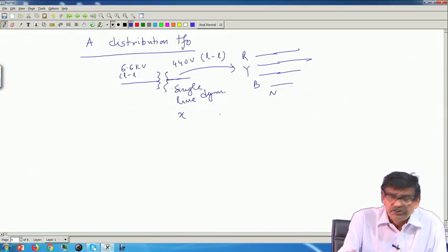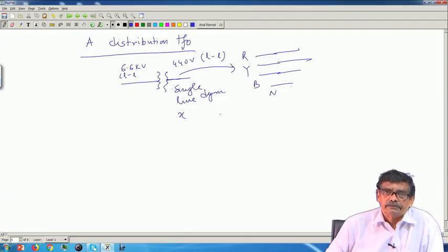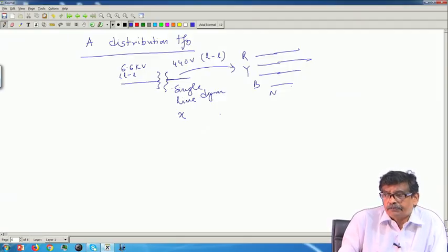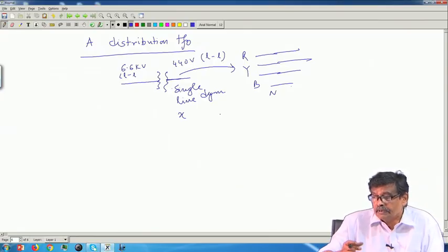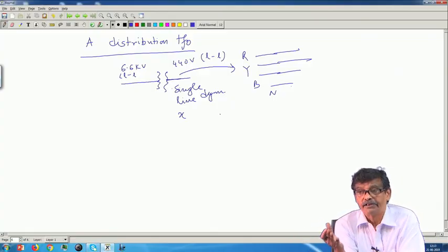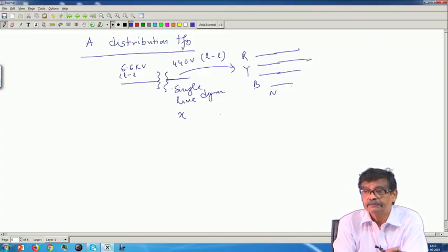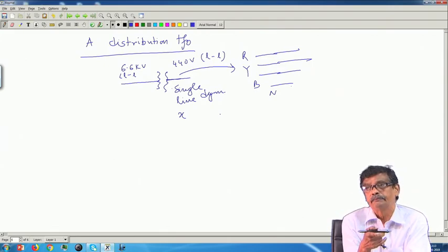Anyway, for a distribution transformer, this is a typical situation. But for a dedicated transformer used in industry, with 8 hours shift duty and all the time the transformer is on and under full load condition, yes, you can very concretely say that I will buy a transformer with x equal to 1.